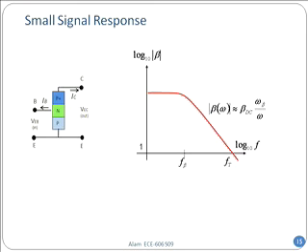But as you try to amplify higher and higher signal frequencies, what's going to happen? At some point the gain is going to drop like a stone, because it's a log plot. Even for one order of change in the frequency, there may be a factor of 10 decrease in the gain. So you started with 100. Now if your gain is all of a sudden 10 and very soon 1, then you don't have a transistor anymore. You cannot catch the corresponding radio signal, let's say wireless signal, and amplify it anymore.